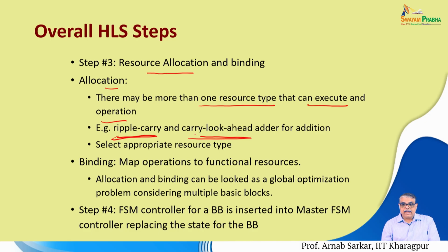And this ripple carry adder can be shared among multiple addition operations, not only within the basic block but also across multiple basic blocks. So for a given type of hardware resource, we choose different types of hardware resources and then assign operations to such types of hardware resources.